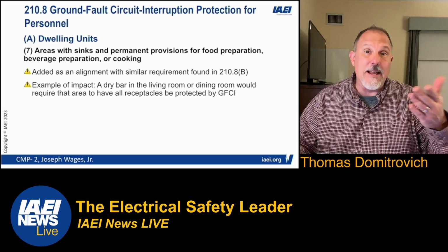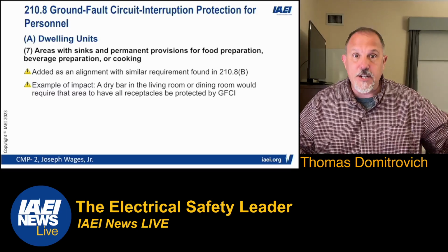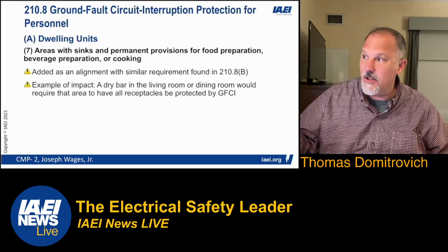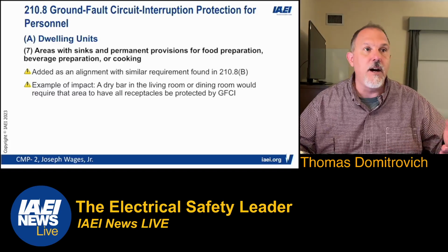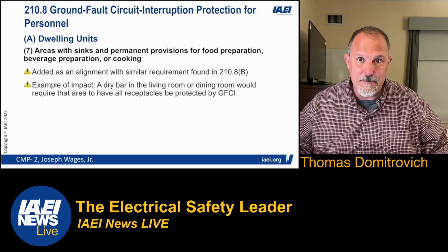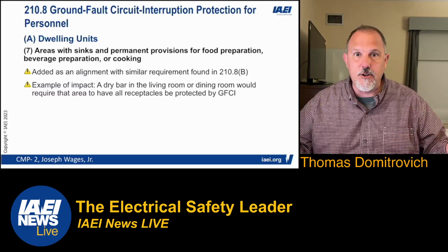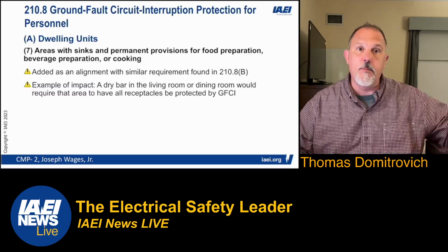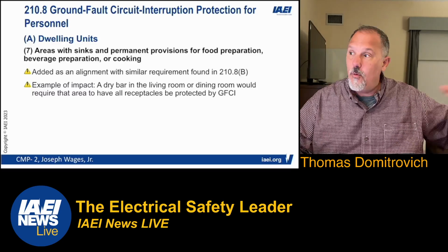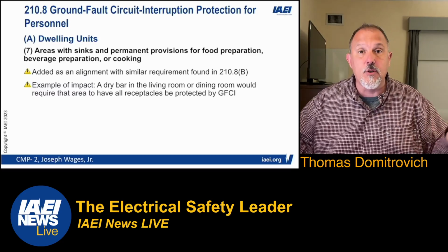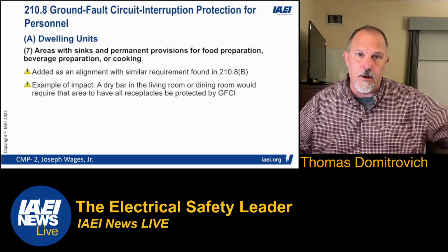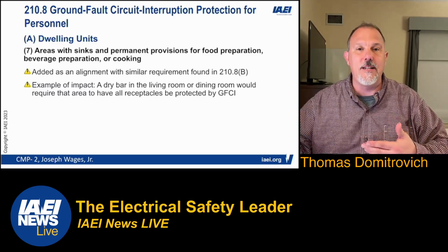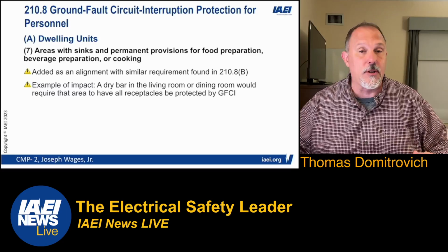Appliances. I mean, the GFCI protection that you find in 210.8 is not because the receptacle is the hazard, it's because of appliances. Right? We're not worried about the infrastructure. If we were worried about the wiring behind the walls, then we would put GFCI back in the breaker. We're putting the GFCI in these receptacles for the most part. You can put it in the circuit breaker, but you can also put it in the receptacle. We're worried about what's plugged into it, appliances. The receptacle is not the hazard.